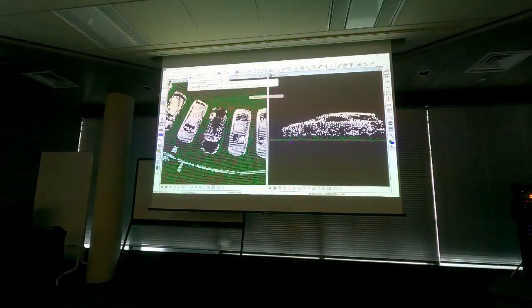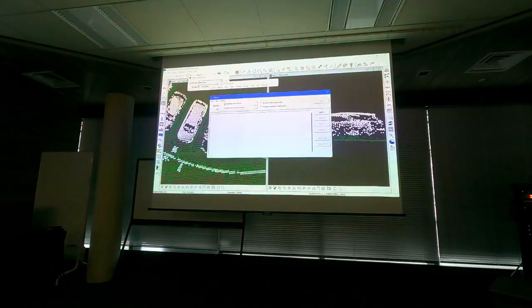So in the macro window, I can say that I want to create a ground per line macro. And then I get the same steps as the match passes wizard would do. Another choice that I have here is height from ground macro. This computes distance, height from ground, and classifies from default to low vegetation, and then from low vegetation to medium, and from medium to high, based on the height from ground limits that I chose in the dialog.